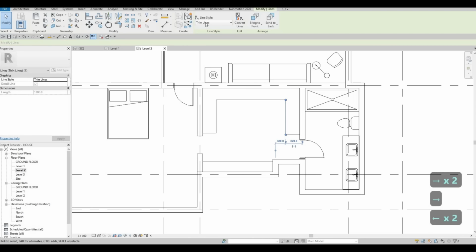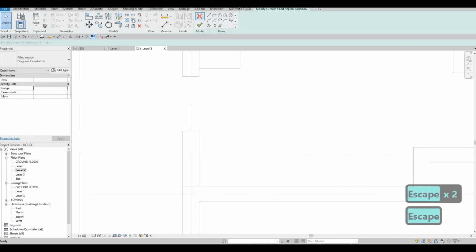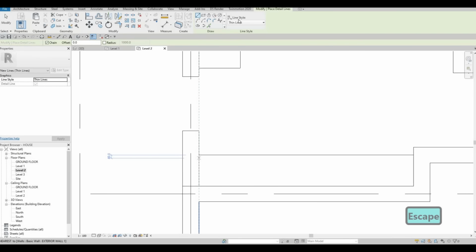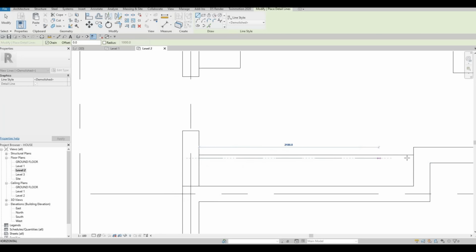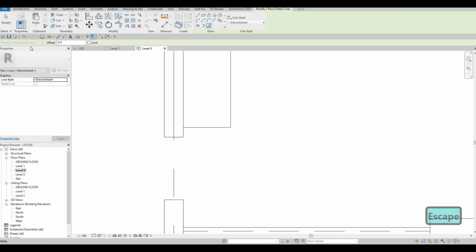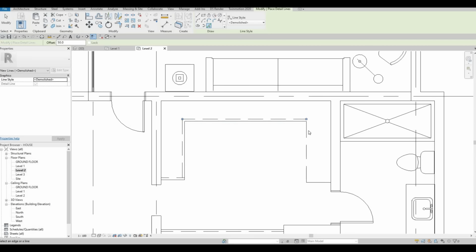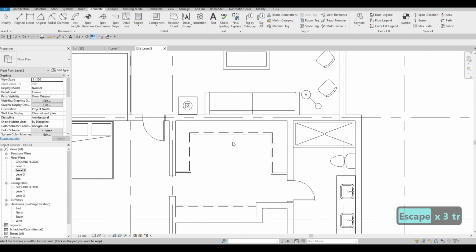And then after that, what I usually do is to add demolish line and then add those details again. So now demolish line added afterwards, and there we go. You can even choose pick line and then offset this one to 50, so that it's consistent in that regard. And then you just need to trim and extend afterwards. There we go. That's good.